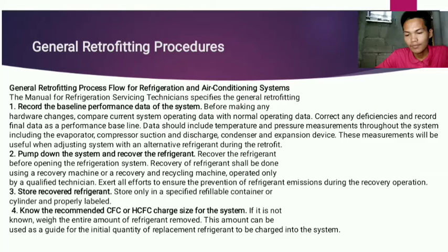Second is pump down the system and recover the refrigerant. So, recover the refrigerant before opening the refrigeration system. Recovery of refrigerant shall be done using a recovery machine or a recovery and recycling machine operated only by a qualified technician.